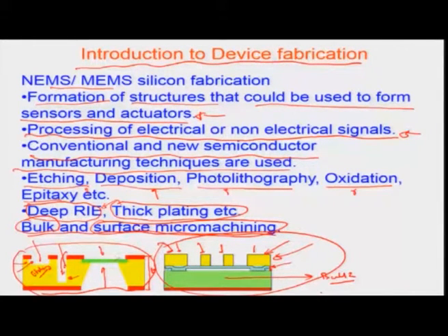This right here, the green region, is P double plus silicon, which is made by doping of the silicon structures. P double plus means that you have a high doping concentration of the group 3 material, which will pump in more holes.